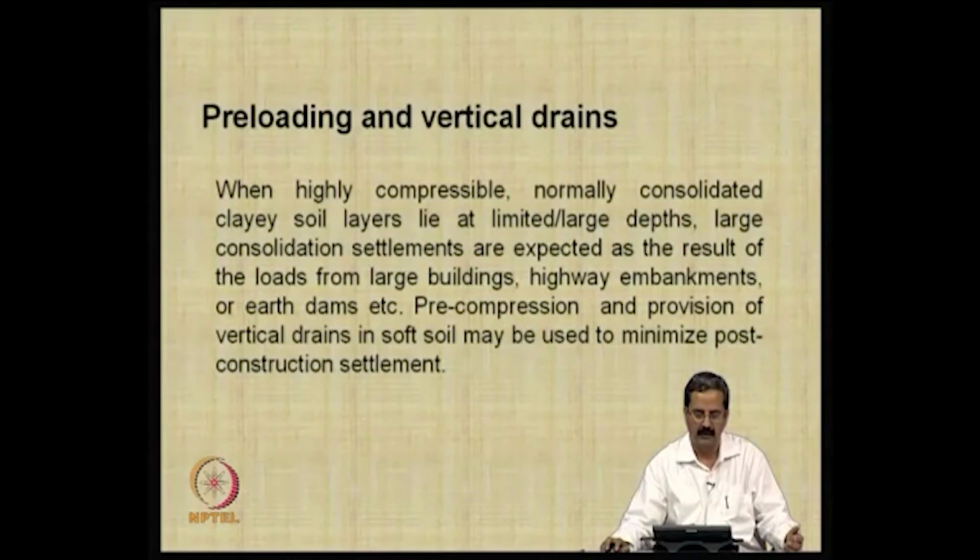The moment you load these soils because of buildings and highway embankments, you end up having a lot of settlements. Bearing capacity of the soil is very low, and how you handle this particular problem in soft soils is something that we will be discussing today.